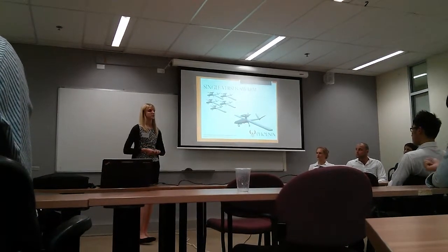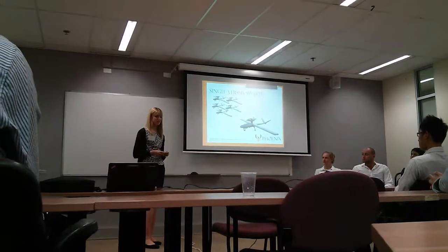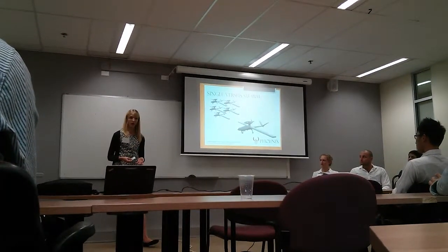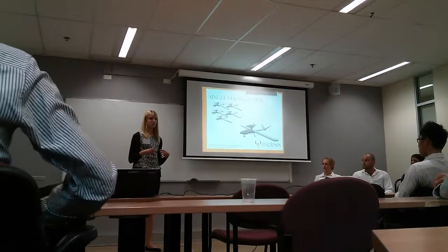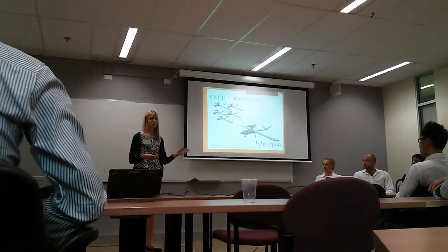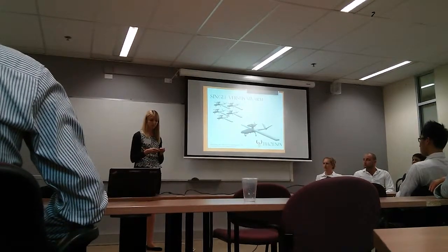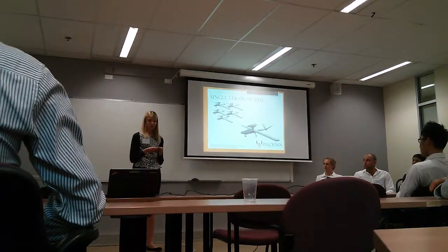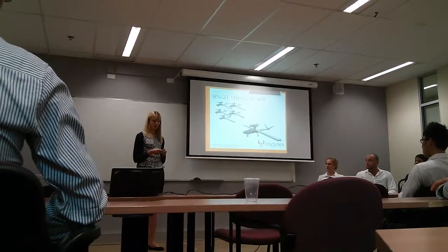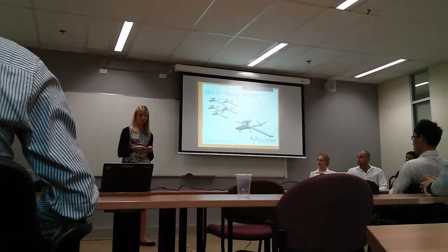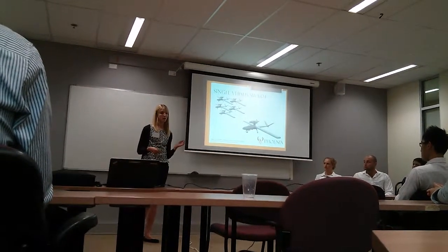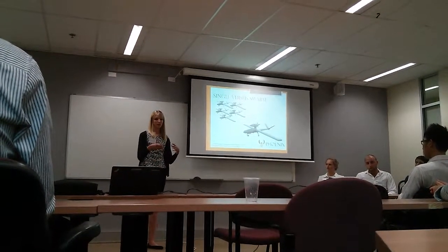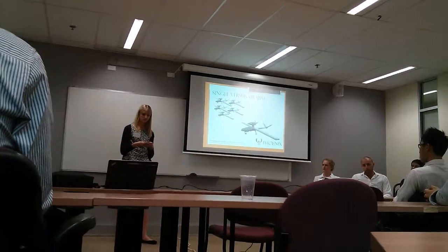The disadvantages of the swarm approach are that the ground station is going to require higher performance. It has to handle a lot of incoming data and also do real-time control for each individual vehicle. There will be an increased maintenance cost because there are more vehicles and the equipment is more complex. And usability is decreased because we'll need pilots to monitor each of those vehicles.